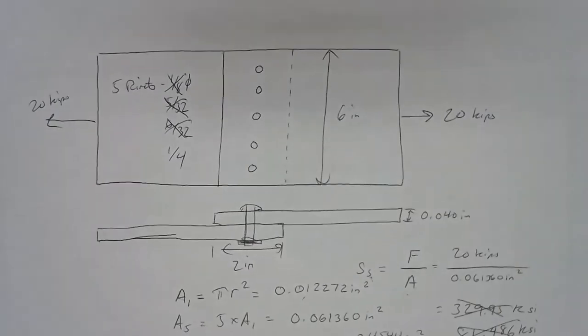They are providing area for shear forces to resolve on. They handle that force because they can handle shear stress. And the number of rivets we've got depends on the amount of stress and force we need to support. So that is the basic idea behind shear stress.